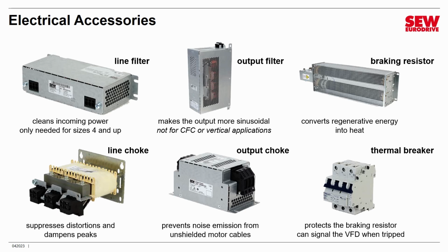And we also sell what are called thermal breakers. These are like circuit breakers to protect the braking resistor if it gets too hot. It can shut things down, and it's capable of sending a signal to the VFD to say, hey, the braking resistor got too hot, I just shut down. So these are some of the electrical accessories. If you question whether you need them or not, speak to one of our application engineers in our regional engineering group, and they will be happy to guide you.